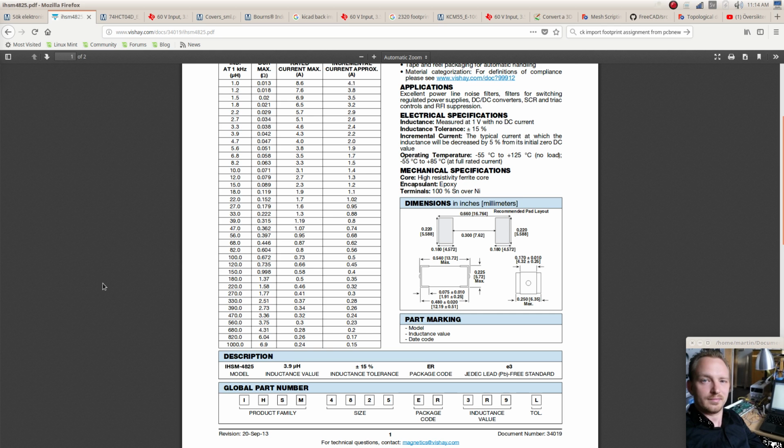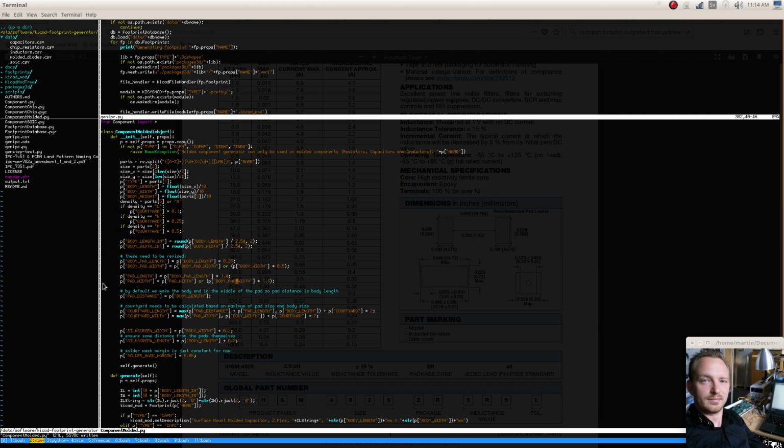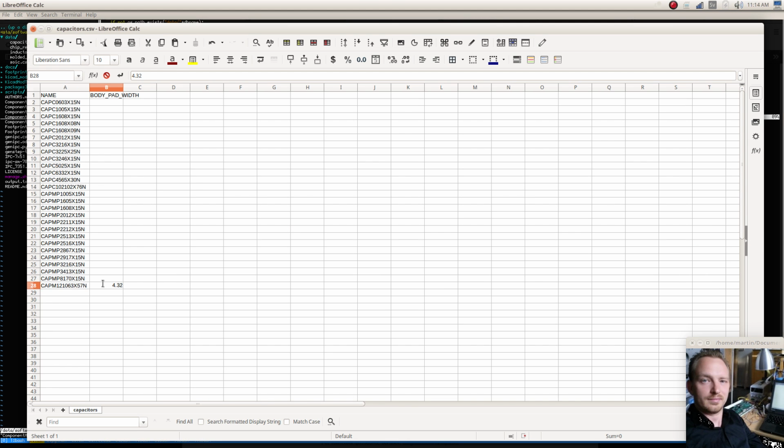And then the pad width we specify as 5.58. So we can actually specify very exact values here. We don't need to use the standard precision here, which is like 1 decimal point. We can specify precise values if we have them. Like that.